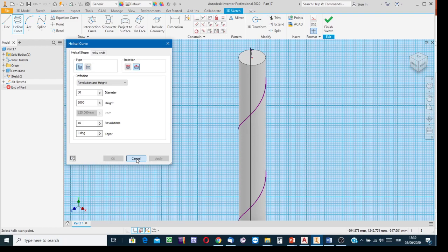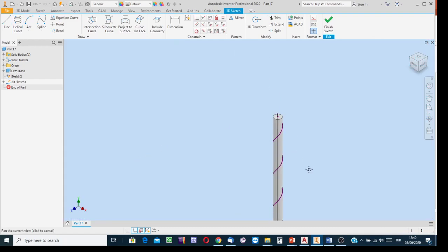Right-handed helix or left-handed helix, depending on the case, either click on this or click on that. Considering the direction of the rotary motion, which is set by the electrical motor, we'll select this option or that option, right-hand screw or left-hand screw. Okay, and then close this dialog box. And then the rest, apply the sweep process.